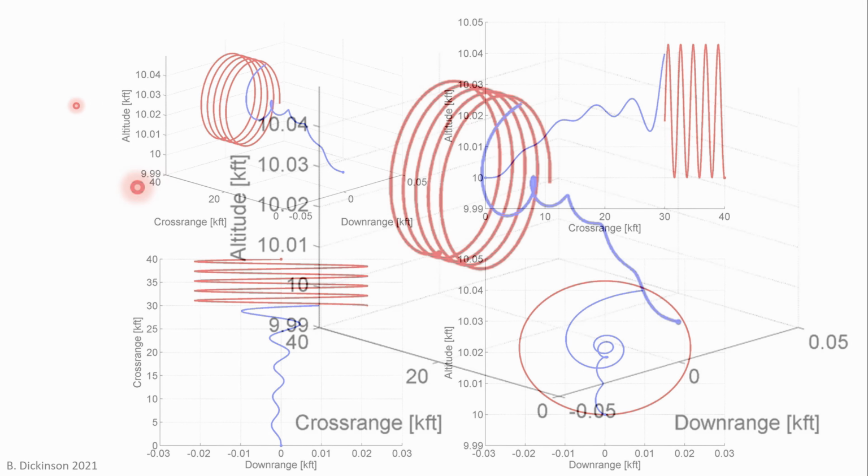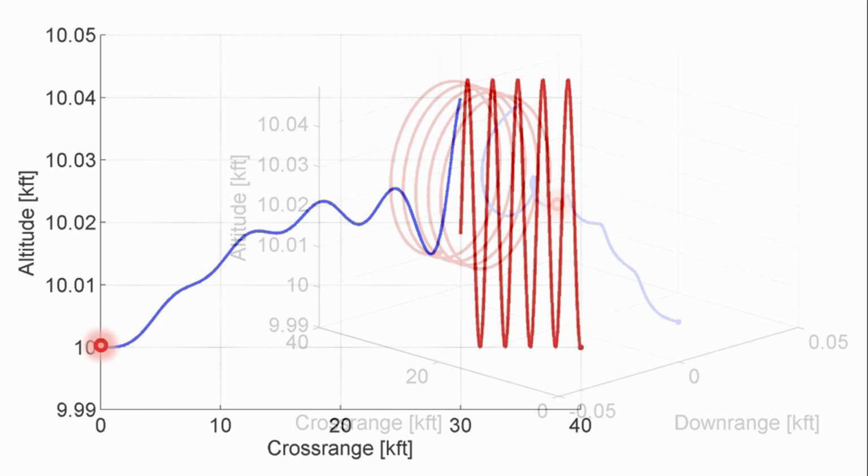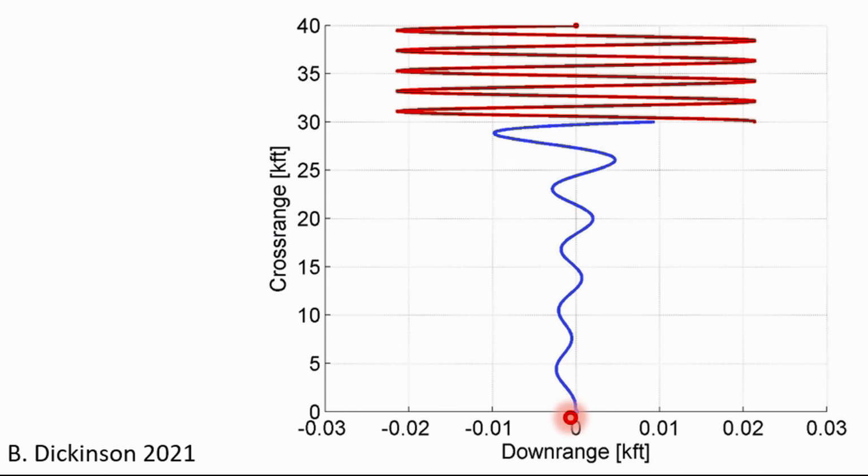If we look at this from different perspectives, we can see the oscillation in the pursuer response. In the vertical plane, the pursuer increases its altitude to the mean altitude of the target and begins to respond greater to target maneuvers as time approaches TF, or time to go 0. In the lateral plane, again, oscillation of increasing magnitude as T approaches TF.